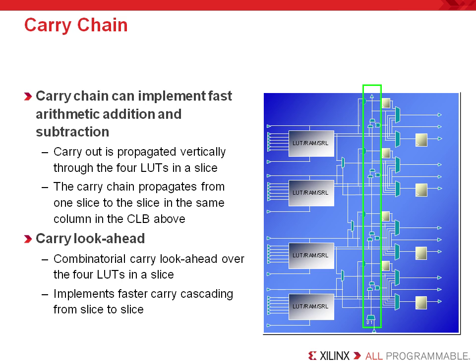Carry logic is the dedicated hardware resource that improves the speed of arithmetic functions such as adders, accumulators, subtractors, and comparators. From the diagram, you can see that the left-hand slices are grouped into one carry chain. Now please note that carry logic propagates the carry signal vertically upward. This is important to note because most designs use carry logic extensively, and by using it, the least significant bit should be placed at the bottom of the carry chain. Likewise, when carry logic is used, bit ordering should be followed by the designer, with the less significant bit being placed beneath the most significant bits.